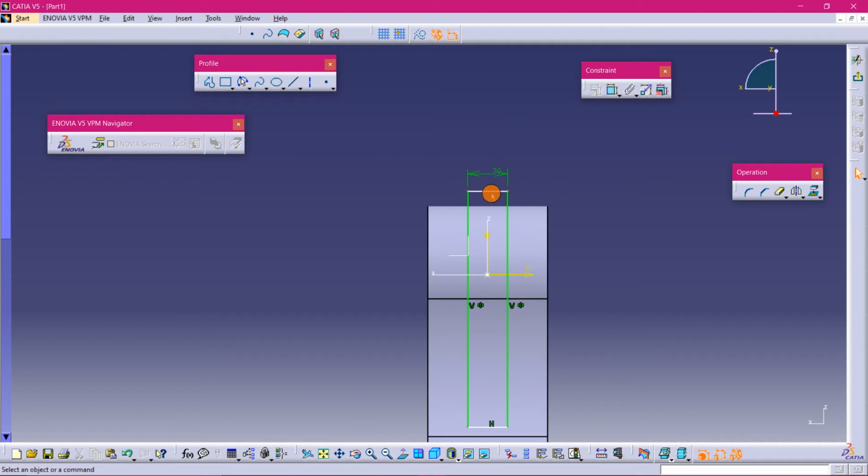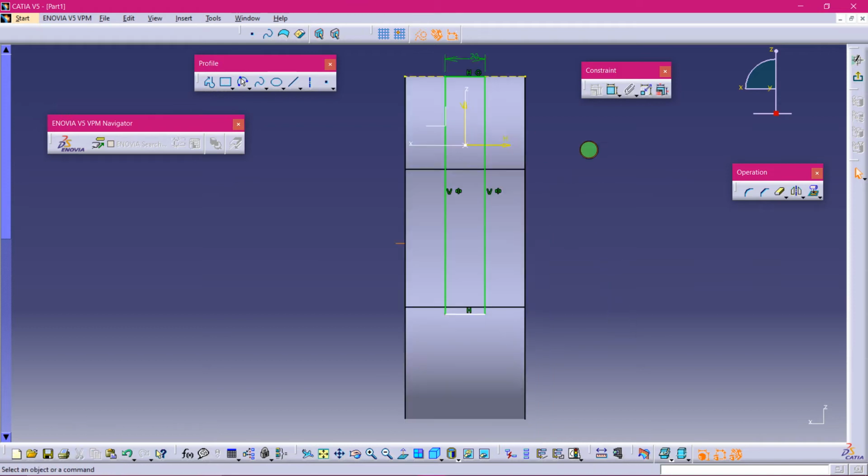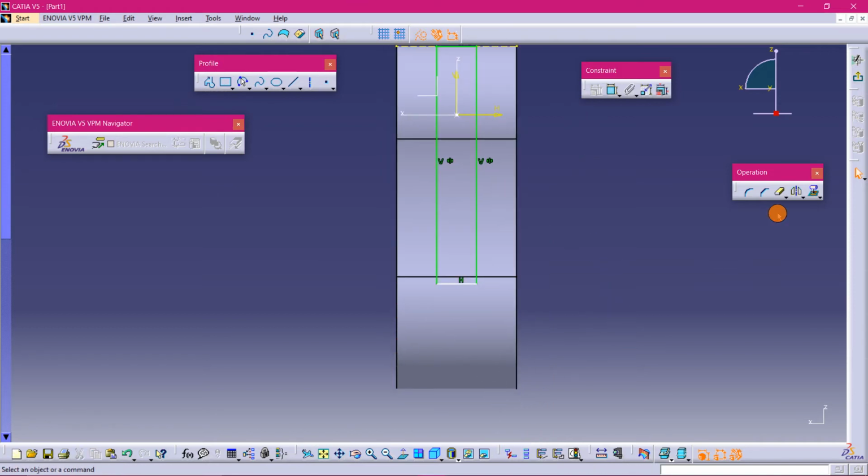okay, this edge is not, so let's give the dimension constraint. And that's not possible. Before that we have to isolate this. So let's click on projection, cylindrical projection, and it's done. Now let's do these both lines coincide. Let's turn this into axis line, and from bottom, even bottom we have to project. Yeah, that's projected, and from bottom it is 30.